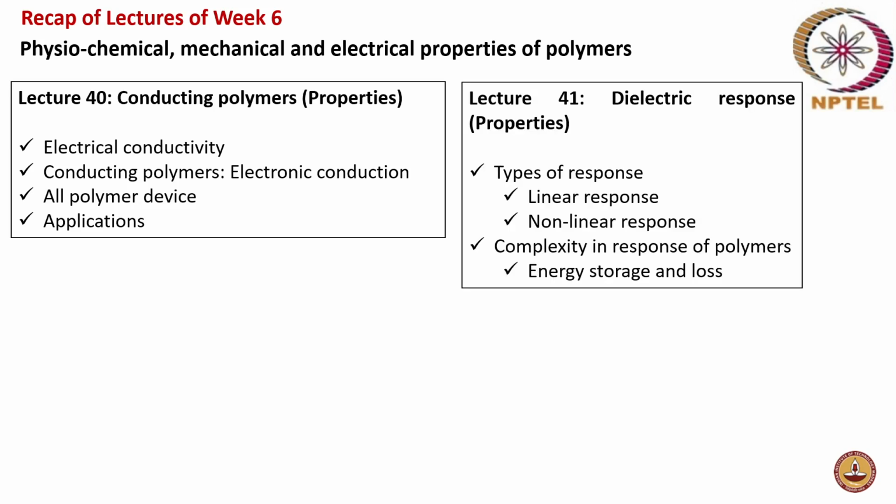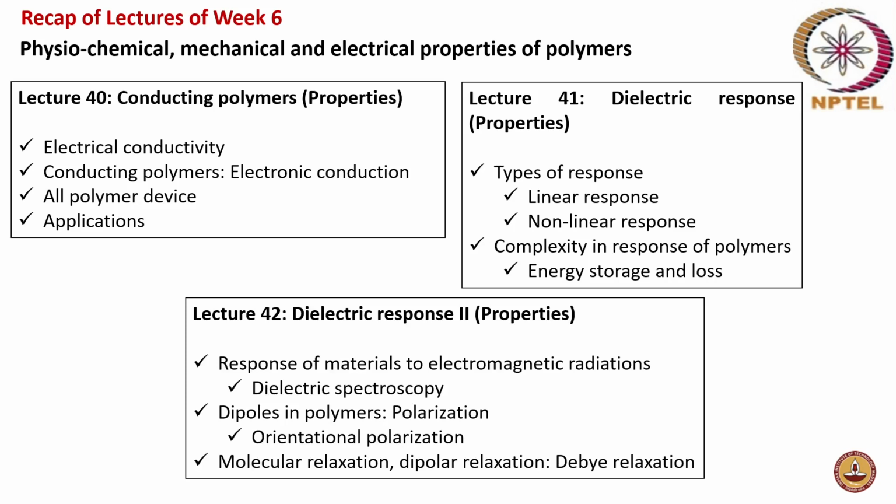The next was on dielectric response. Here there was a basic discussion on linear and non-linear responses, and then complexities in response of polymers, and then energy storage and loss. And then the next lecture was again on dielectric response of polymers. So response of materials due to electromagnetic radiation. There was a detailed discussion on dielectric spectroscopy, and then dipoles in polymers, orientation polarization, molecular relaxation. Debye relaxation was discussed in detail.